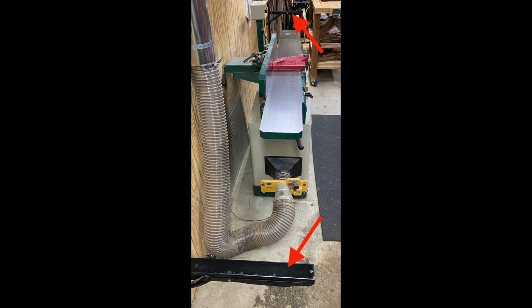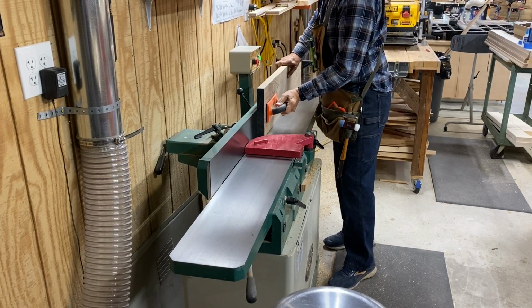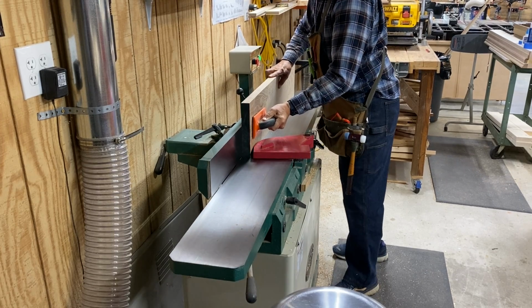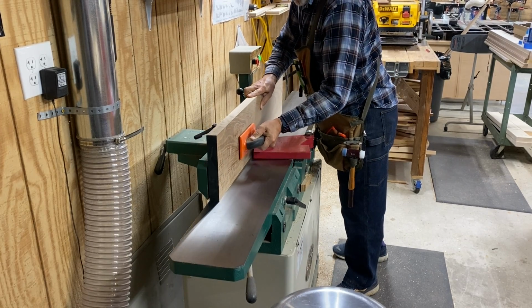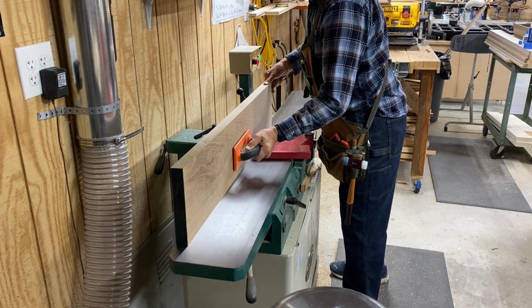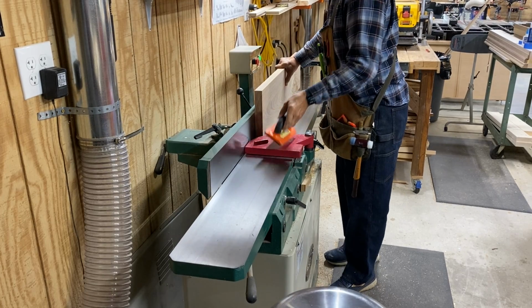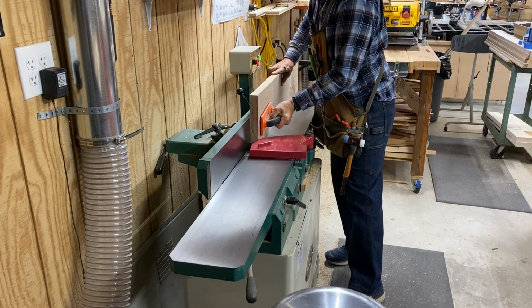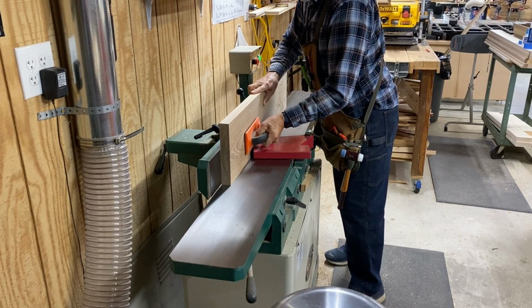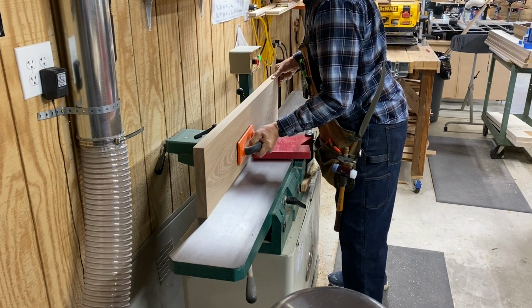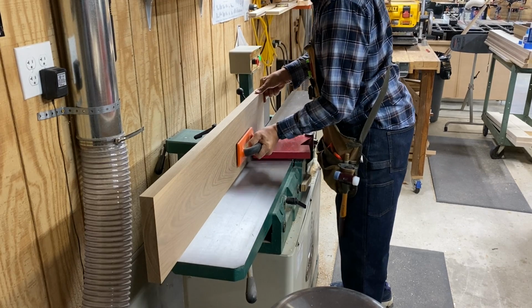To joint an edge square to its now flat face, place the freshly jointed face firmly against the fence. Use the same downward pressure technique as you did when jointing the face. Make sure you use a push pad to push the board against the fence, preferably at a point just past the cutter head. Fences flex, and this assures consistency if you push in the same area. Make enough passes to remove a pencil line marked on that edge.